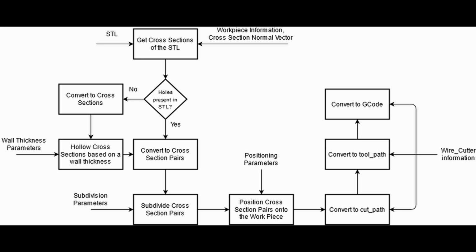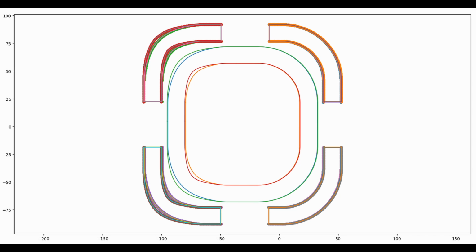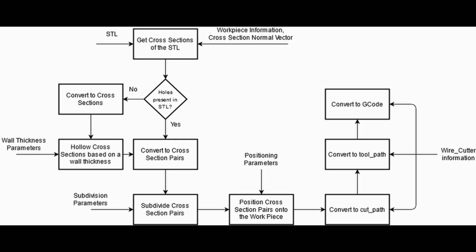And the reason you want it hollow is so that we can subdivide that cross section into a bunch of smaller pieces that don't take up as much total area because the internal hole no longer is a hole. It's another exterior part on the opposite side. So once you subdivide all these pieces into, say, four new cross sections per the global cross section, instead of, say, 50 cross sections, now you might have 200. But these 200 don't take up a whole circle with a large hollow space in the middle.